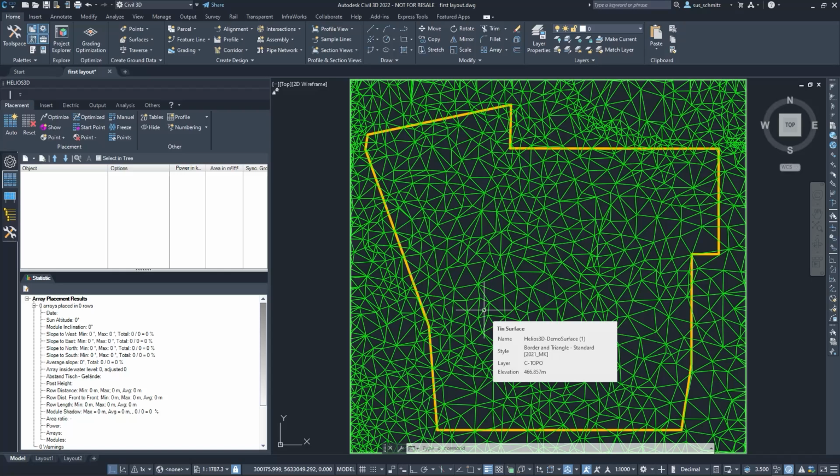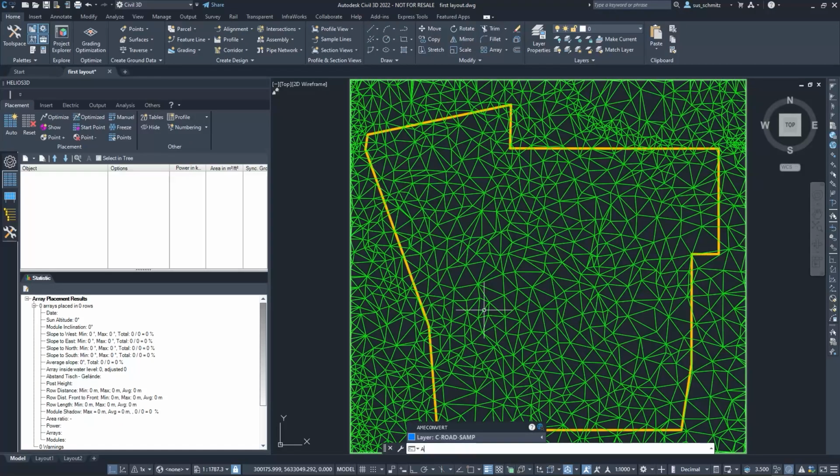Then we need to set the coordinate system. That information can only be retrieved from the original data source. There's no way to guess that information. One way to do that would be the map status bar. So when the map status bar is shown, you can just go to the bottom line and choose the coordinate system from the library.